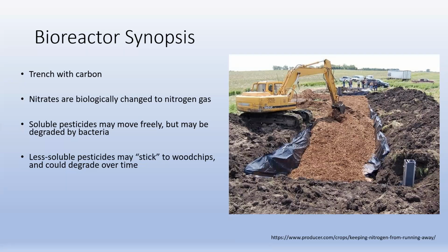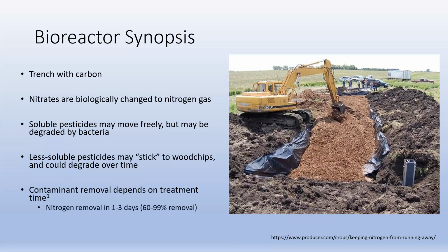Soluble pesticides, those may move freely. They're dissolved in the water, but those may also be degraded by bacteria as they pass through. Less soluble pesticides are likely to stick to the wood chips, and those could also degrade over time, so they'll bind and stick. The big thing from my research was that contaminant removal is going to depend on treatment time, how long you're going to have water sitting in there.